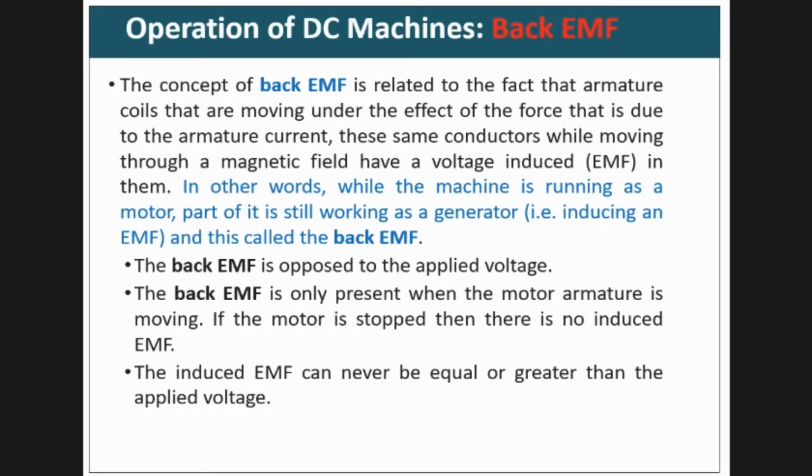So the back EMF is related to the fact that the armature coils are moving under the effect of the force that is due to the armature current in the case of a motor. These same conductors, while moving through the magnetic field, have a voltage induced in them.